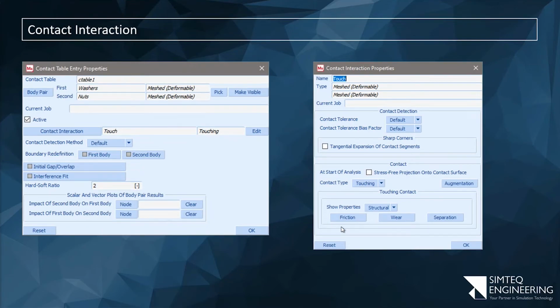So in the model that we've looked at, this bolted connection, since it's mostly the same material connected to the same material, it's convenient to define a friction coefficient for specific pairs. So these are the settings that tend to be set for a subset of the model. It's stuff that a large part of the model will have, so that's why we set that on the interaction.